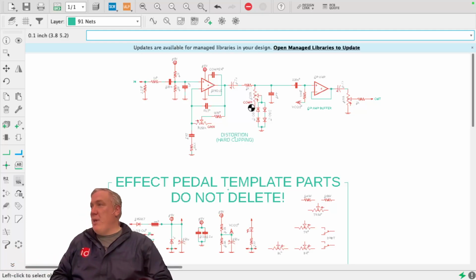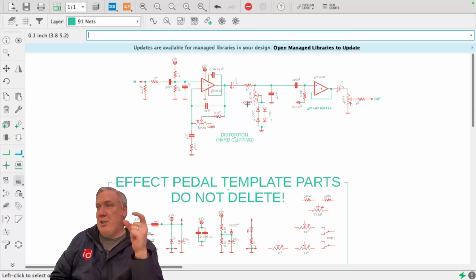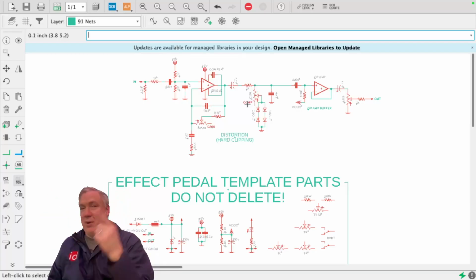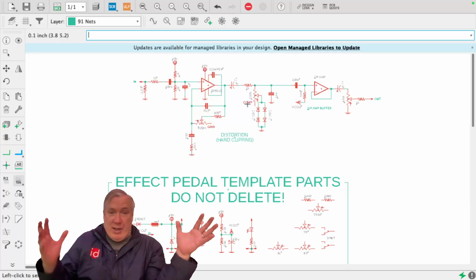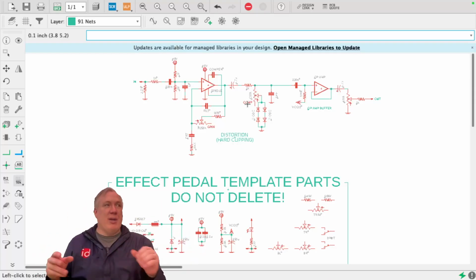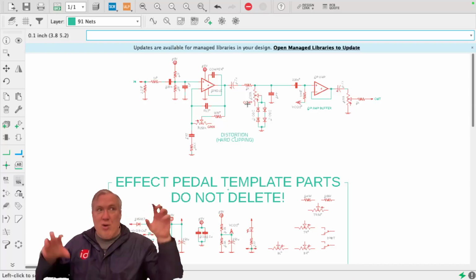That may mean that suddenly we have way more actual physical chips than we need, because an op-amp chip can actually contain up to 4 op-amps. So I might have 4 schematic signals, but it's only one part. And that makes it way simpler to build your circuit if you can do that. But right now, because we've been combining things from multiple modules, you might have 4 op-amps and literally have 4 chips.